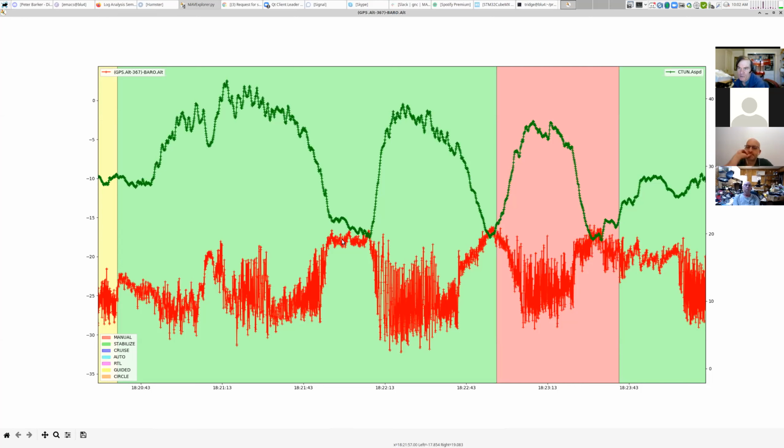So what we're seeing here is, I guess you call it a Venturi effect, where he's getting airflow past the side of the cube, past that little USB port. As he gets high-speed airflow past that, his baro is changing quite significantly. What we're seeing is it's getting a higher altitude estimate because it's got lower pressure, because it's sucking the air out of the cube. As the air is rushing past, it's sucking it out, lowering the pressure, which means it thinks it's at a higher altitude, and he gets close to the point where he could crash into the ground.